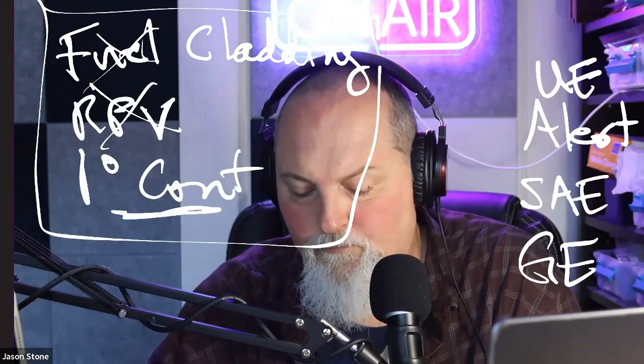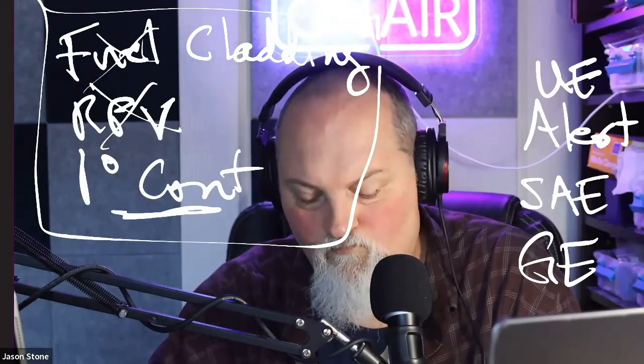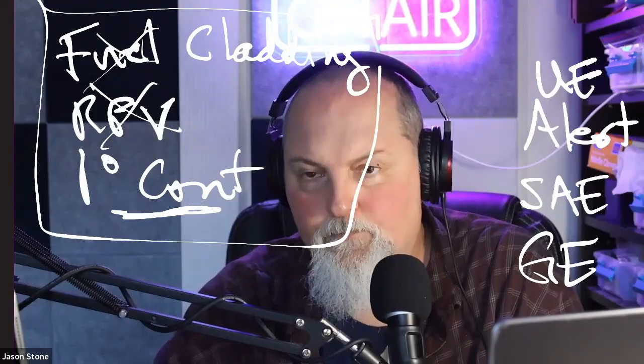Any questions on those four? No, I think I got it. So for the SAE, it's a loss of just those three barriers. Any two of those three. Yeah. And for these emergencies, remember we have six barriers, but these are the only three barriers we worry about. These are the only three we care about for our accident response because those are going to be the three that are really indicative of a problem that can dose the public.